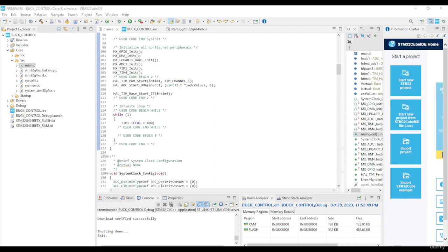First, the first part that has been ascertained is that the duty cycle can be changed. That's great. The second part is that the timer interrupt is being triggered, and that's very important to actually execute the control code. And obviously, the third part is ensuring that we can actually read the output voltage and output current with the equations that have been proposed in the previous section. Those three things are absolutely important to obtaining closed loop control. If one of those is not set, then nothing's going to work, basically.